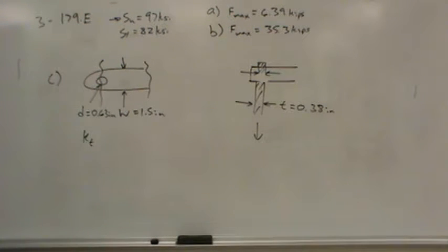But to do that, we'll have to go to the back of the book and look up the stress concentration factors. What kind of loading do we have? Which figure should we look at? Well, look at page 727, and you'll see a picture that looks a lot like what we have. So here's the basic geometry that matches our loading situation or our design situation.